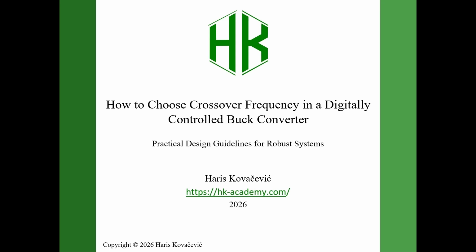In many design guides, you will see the recommendation: choose your crossover frequency to be around one-tenth of the switching frequency. That works reasonably well in analog control, but in a digital control buck converter, things are different. We have sampling, we have computational delay, we have zero order hold effects. So the question is, how do we choose crossover frequency correctly in a digital system? In this video, I will give you practical design rules you can directly apply.